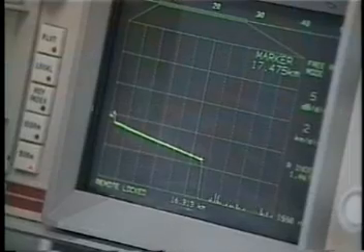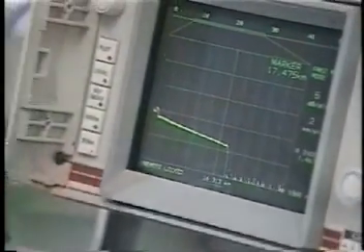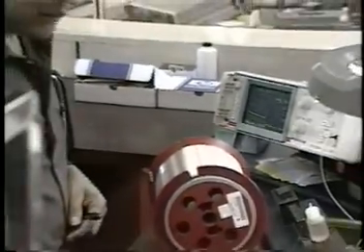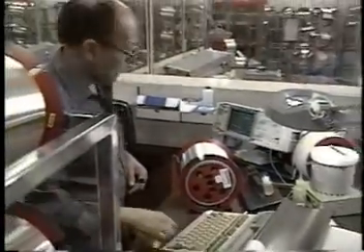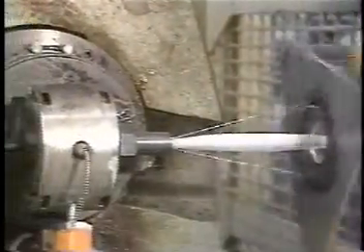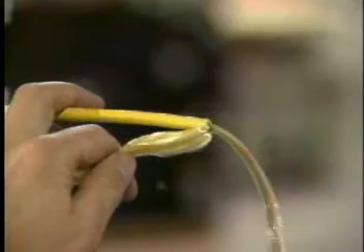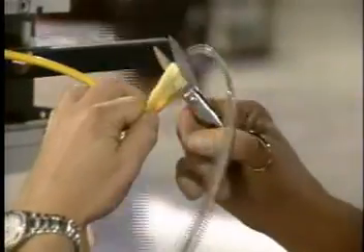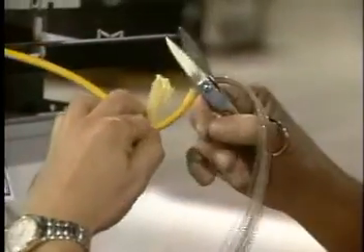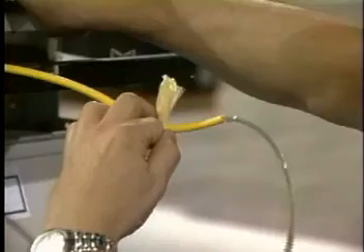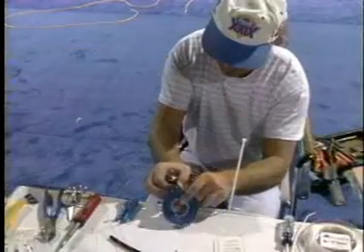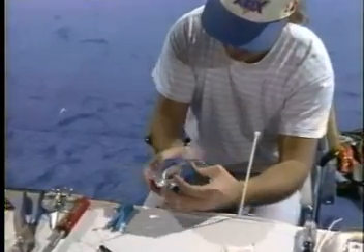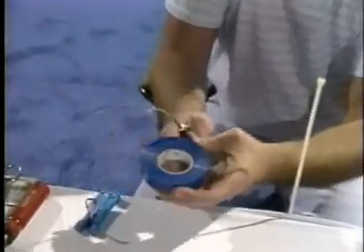All optical fiber must pass rigid quality control tests before it can be used. Fiber that has high losses or is mechanically weak is rejected. The fiber can then be incorporated into cable structures. All transmission lines, including optical fiber, exhibit some loss or attenuation of a transmitted signal. In fiber, much of the loss is intrinsic, that is, due to the glass itself. However, external conditions, such as excessive bending, connectors, and splices, also contribute to signal losses.